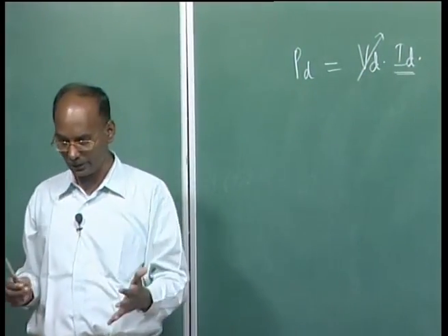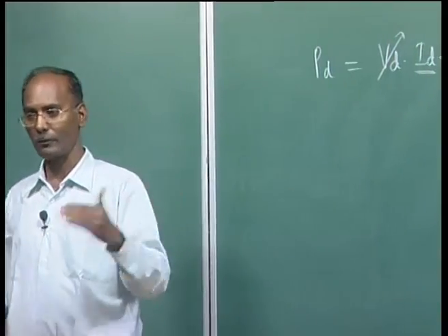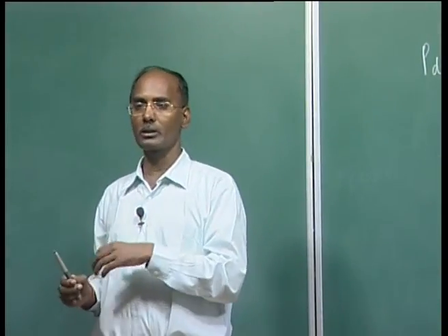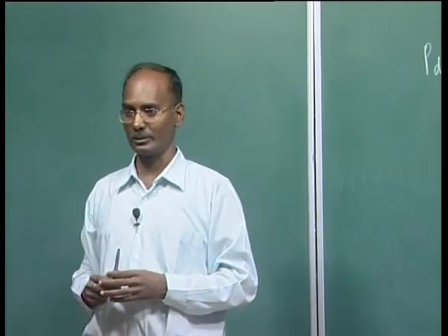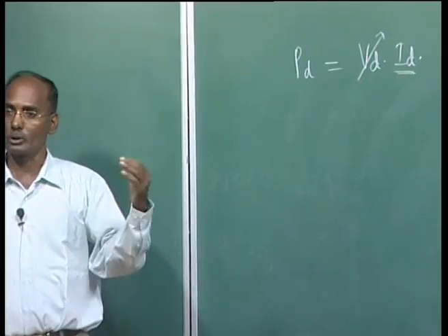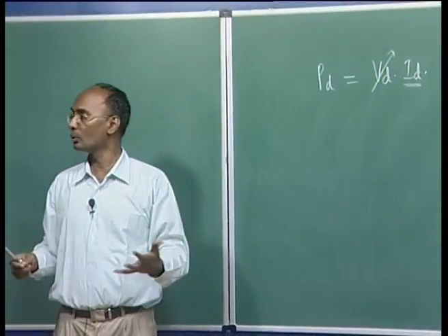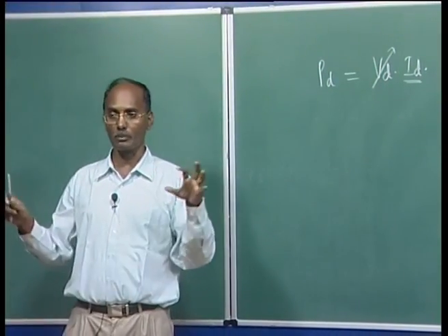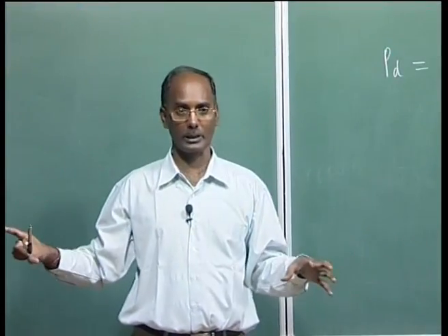If you operate as a rectifier, you change alpha, and if you operate as an inverter, you change beta. Once you do this, the reactive power requirement changes, and therefore you require huge reactive power support at both the rectifier and the inverter end.